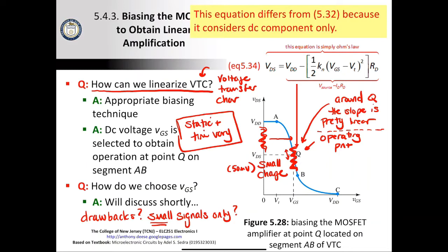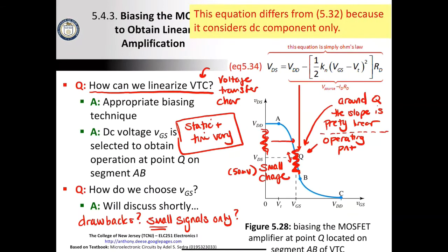So, I mean, it can take the 5 or 20 millivolt sine wave and create a 5 volt output. But the magnitude of the input is going to be relatively limited. And we'll play around with those values when we get to some of the examples, and you'll see what you can and can't do. Again, this is really the most basic type of amplifier. So if you want to build something with a wider operating range that has a more robust voltage transfer characteristic, then you're going to need to use more than one device and some more advanced design techniques.